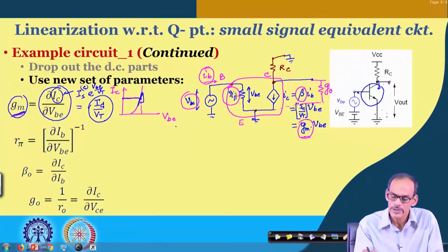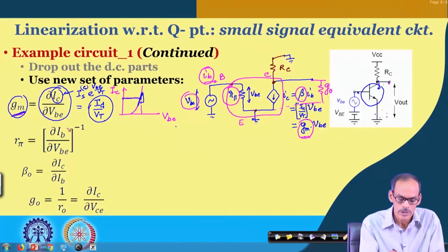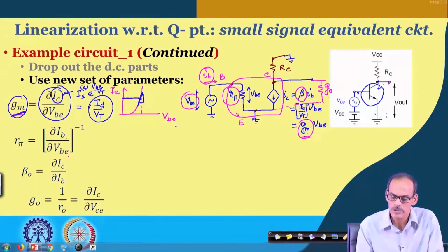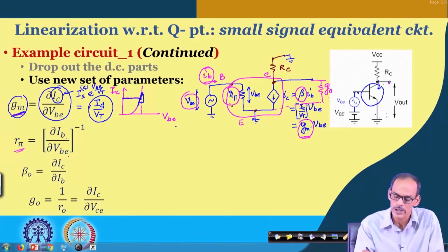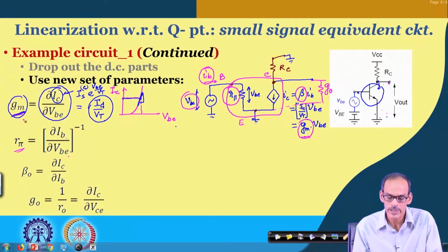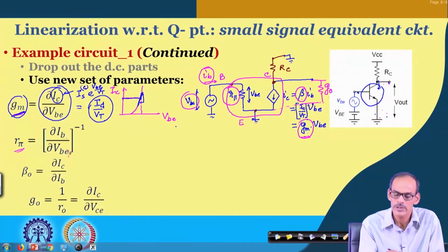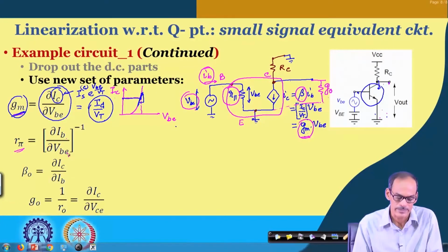So, if I observe the conductance here, namely the variation of the base terminal current with respect to VBE, then equation-wise it is dou IB divided by dou VBE. That is the input port, or base to emitter port, conductance. If I take the reciprocal of that, it represents the base to emitter resistance, r pi. Later I will show why we have different subscripts, but at least we understand that the unit here is ohm. So, we call this the base to emitter resistance.